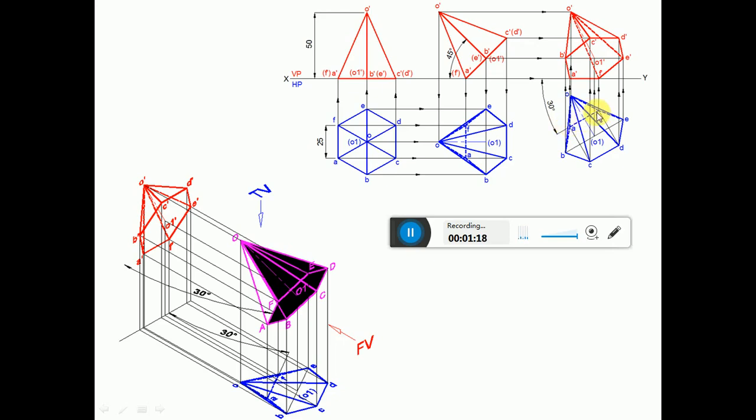Once you get this line AF, then from A, by using the compass, you measure the distance from A to this point. Similarly, from A, you mark that point here. So this axis OO1 is perpendicular to this AF. So from this point, by using the protractor, you measure an angle of 90 degrees with respect to that inclined line, and then you draw a perpendicular line here.